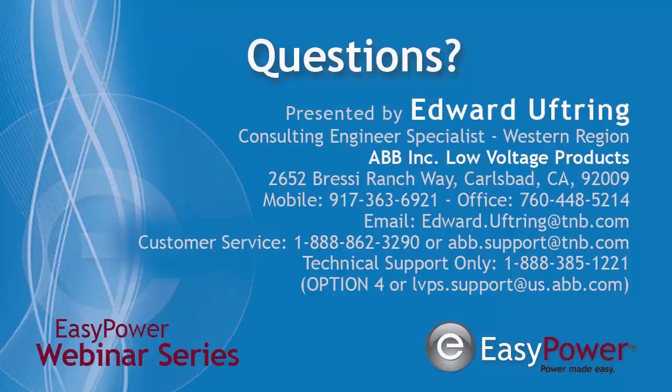You can set how far and how long you want that time delay to be and what actual trip protections you want to activate. So in an LSIG breaker, you can actually shut off the instantaneous and just use the L, the long delay settings. So for that, it's up to, again, the application that you're using, and the studies that you use should really determine that.